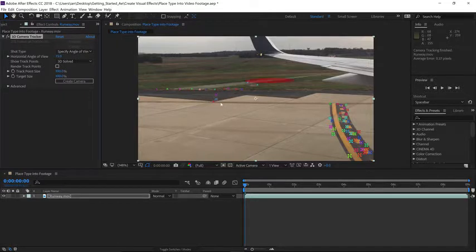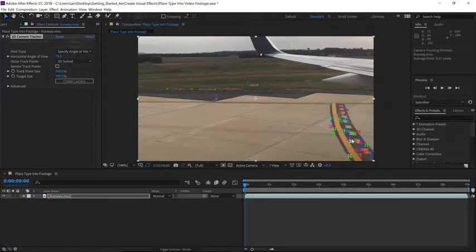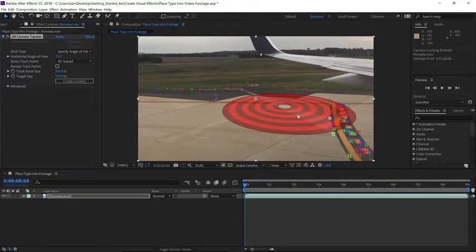Now when I hover with my target, it's still got a little distortion close up here, but it's nowhere near what it was before. And when I'm out here, there's far less distortion. So I'm going to hover around this general area, and I want my target to look like it's actually sitting on the tarmac. If you notice, as I'm moving my mouse around the scene, I'm getting 3 points that create a triangle, and if I click, those 3 points will be selected.